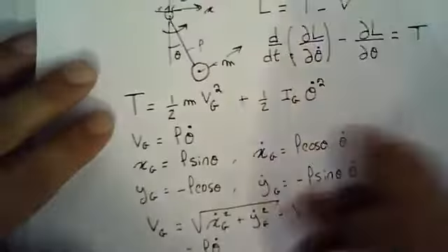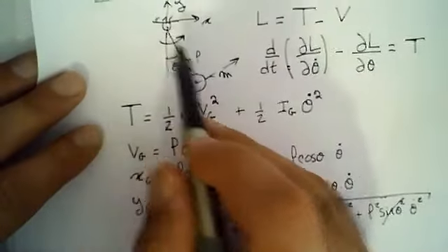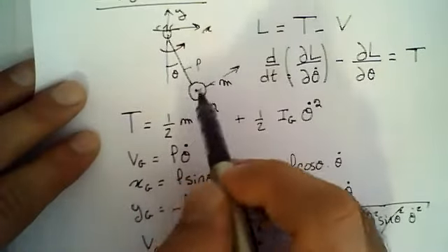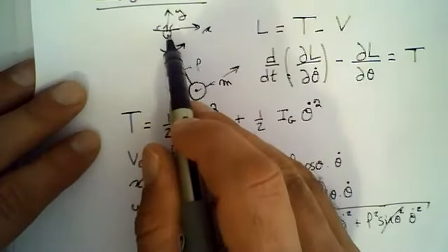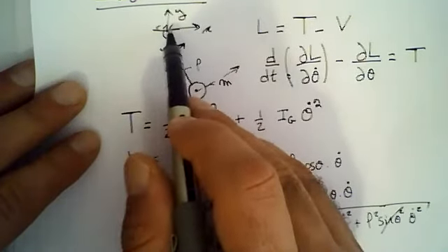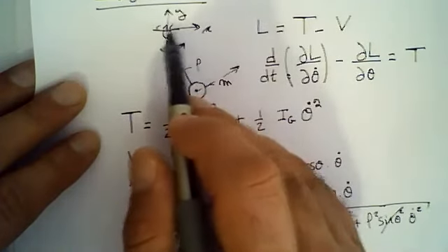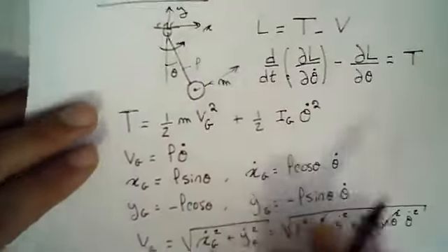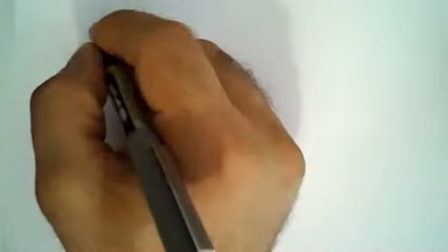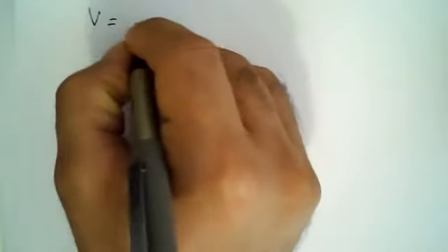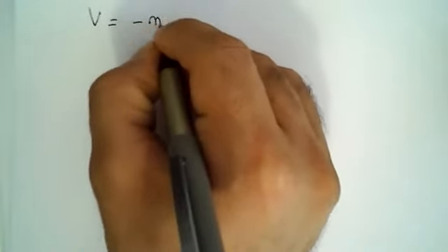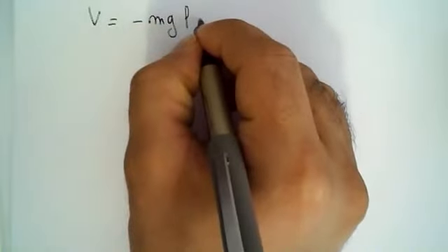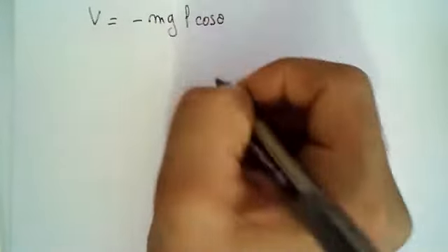So what is the potential energy here? Very quickly, you can choose anywhere that you want for your reference, right? You can choose in the middle, at the bottom. It might be a good idea to use the base frame, so that your Y here basically will give you the potential energy of the system, right? So what is my potential energy here? We said it's equal to V. So my potential energy, if I choose the top, will be minus mgL cosine theta, right?